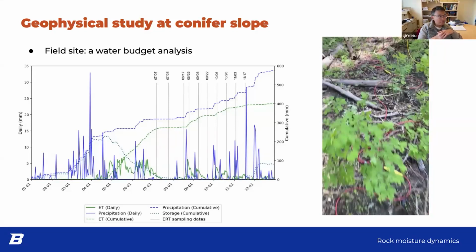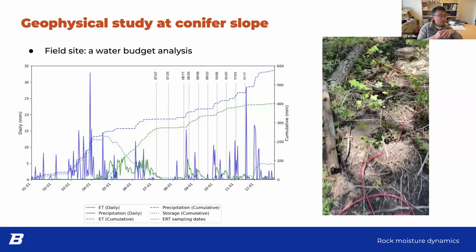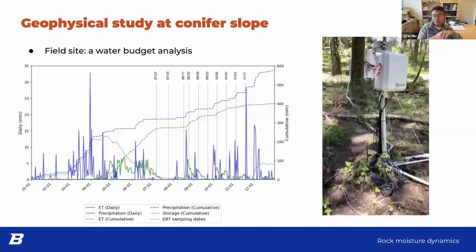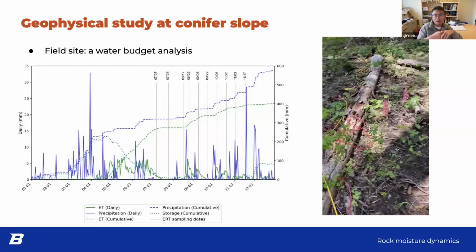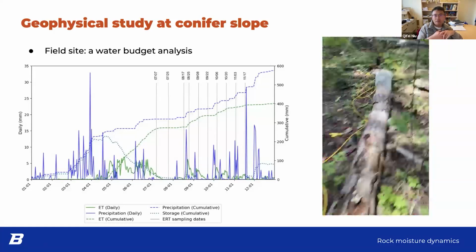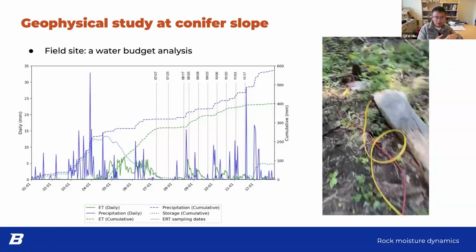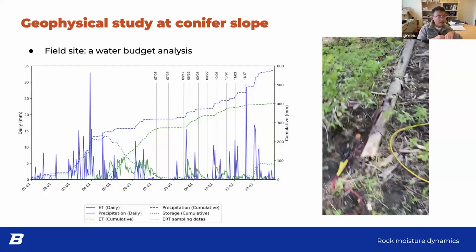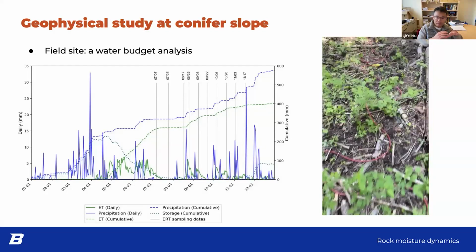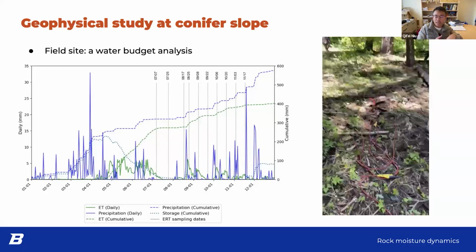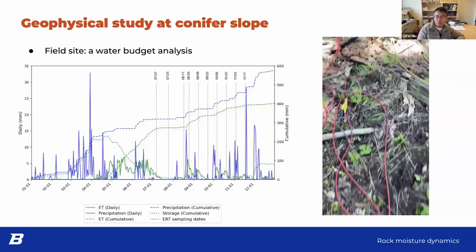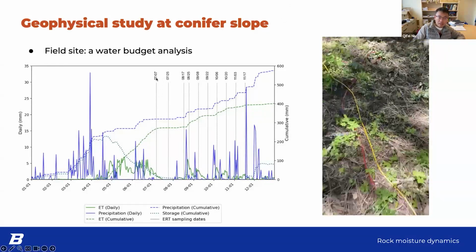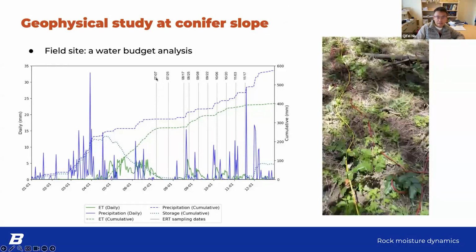The first test is the seismic method. The purpose of the seismic method is that we are trying to get the velocity image, so that from the velocity image we can know the soil layer and also the fractured bedrock layer. And then from there we can divide the subsurface into different regions, and then we run the electrical resistivity monitoring over time. And those lines there indicate the dates that we collected the data.